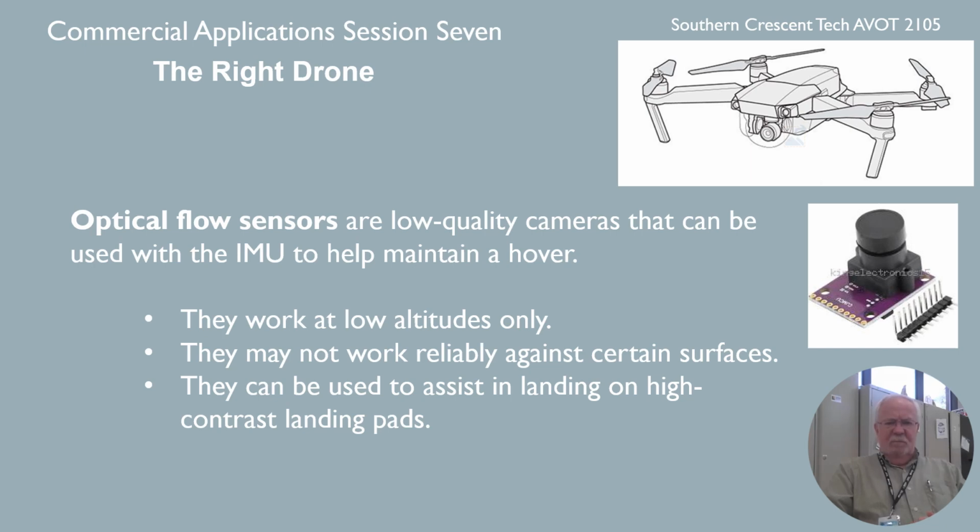Anyway, it depends on the surface, of course, how well it works. And for landing, if it's a surface that has no markings, just bland, flat, consistent color without any kind of thing to compare, it doesn't work too well. So using a landing pad helps in that situation. Water is also a place where you can get into trouble. If it's a fairly low quality camera that's used for landing assistance, flat water especially can deceive it, and it won't know how high it is above the water, and it may settle into the water. That seemed to be a problem. That's less likely nowadays. It used to be a bigger deal.